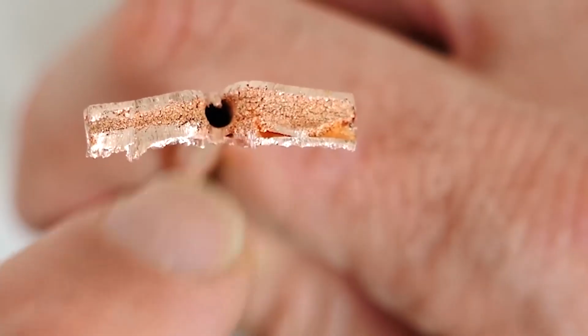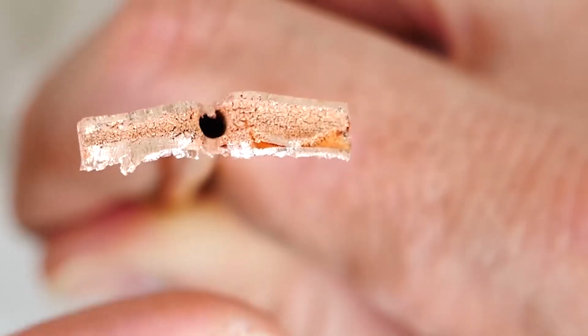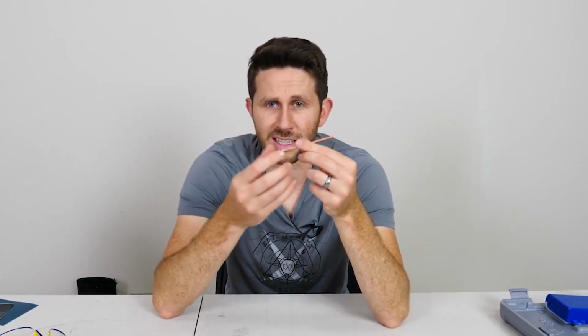And the spongy inside of the pipe is so that the water can get wicked up onto the sides of the pipe. So then how this heat pipe actually works is it's made of copper, and so you still get the copper conduction itself. But the magic comes from the water vapor inside of it. So the tube starts off at a very low pressure, but as you heat up one end of it, the water that is at that end of the pipe heats up. And when it heats up, it vaporizes. And as it vaporizes, the pressure increases.